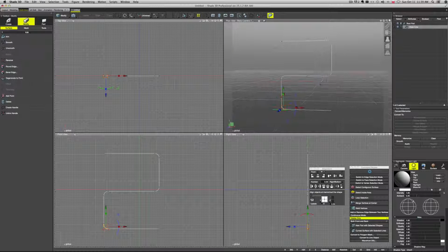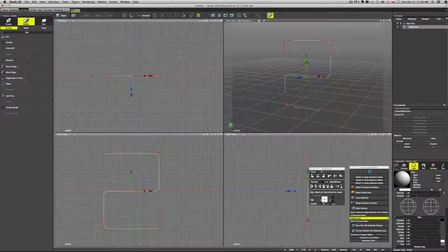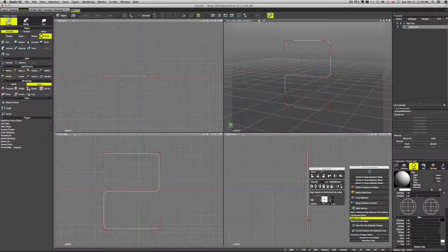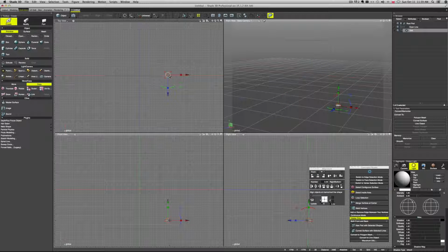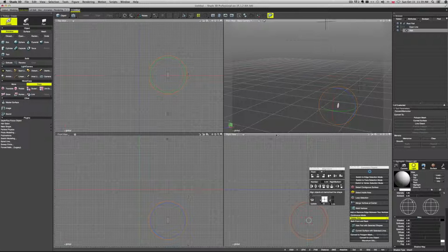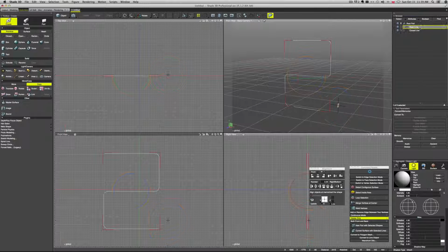And now that we have it, let's create something that we can sweep along it. So maybe let's create a small circle. All right, anywhere is okay. Now let's press Shift and turn it precisely 90 degrees. And our disk, let's convert it into a line object, so it changes into a closed line. So we have an open line and a closed line. Now our open line, let's click here and memorize it. You can see it's emphasized, like this thicker white line now.